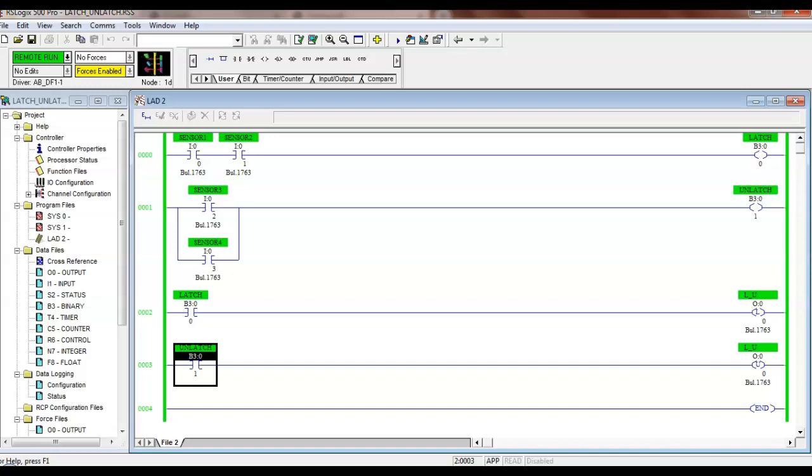So we got one of those. It had 2 coils on it. One of them you would energize to cause it to latch, and then you could turn that off, and it would stay what? It would stay latched until we unlatched it. So that's the only place I remember them being out there, on every radio control crane that we had. We had that latching relay on the magnet circuit.